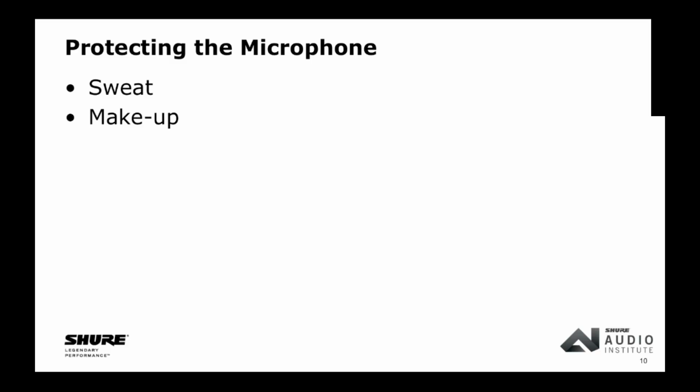Because most of the elements now have some level of water resistance on them. But back in the day, before they did, there used to be a phenomenon that we would call the mic's gone supernova, where the mic would actually start to increase in electrical conductivity because of the sweat and the electrolyte in the microphone head. It would get super loud, not particularly good sounding, but it would get really, really loud, and then it would just die. Wow, that's interesting. Supernova is a good term for that.